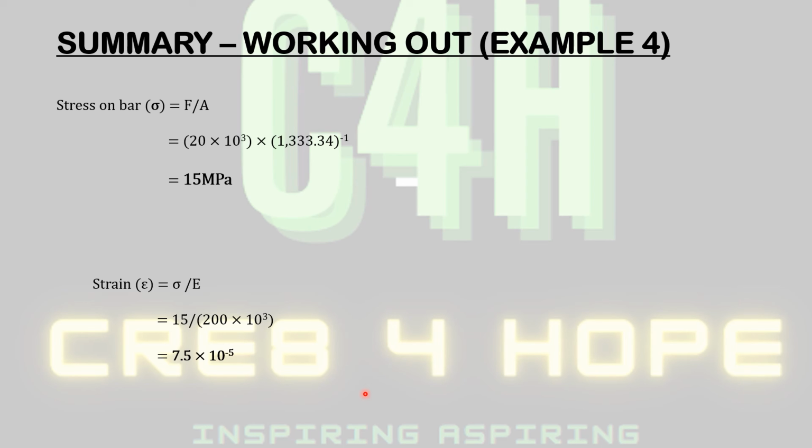So that would be 15 times 10 to the power of 6 divided by 200 times 10 to the power of 9. So if you divide 10 to the power of 6 by 10 to the power of 9, you're left with 1 over 10 to the power of 3. Okay? So we do the computation and we get 7.5 times 10 to the power minus 5. So that is the calculated strain.